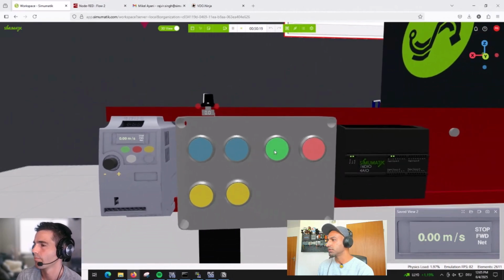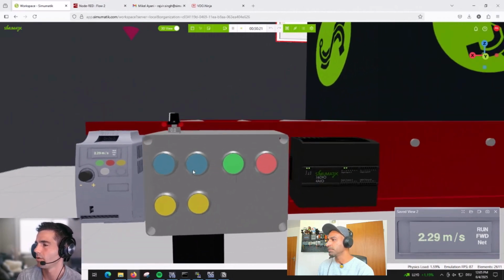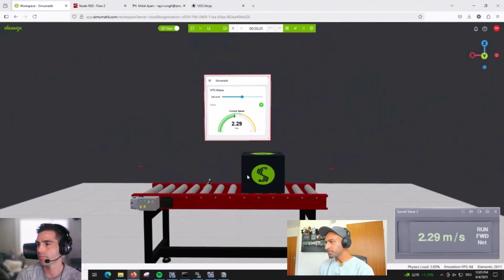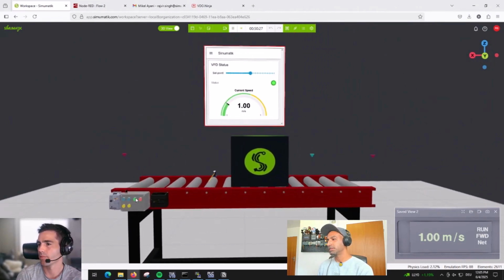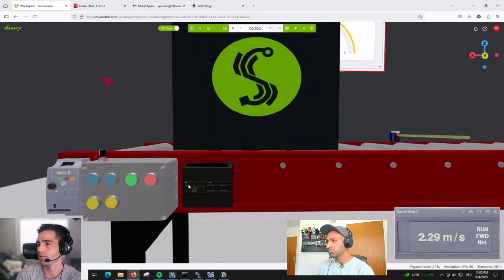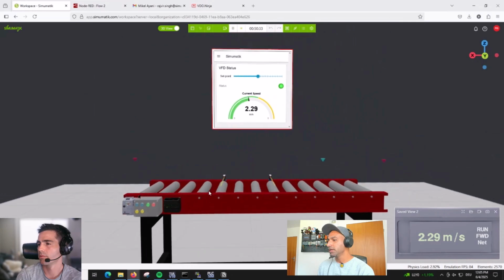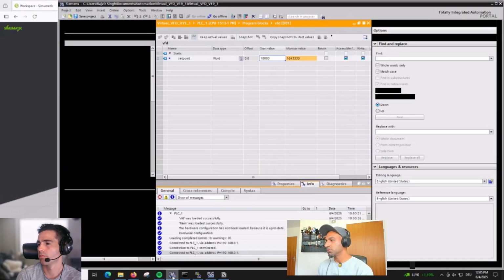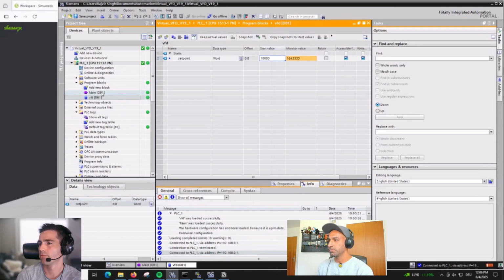So this is just simple on-off control. But the question is how the signal is moving. From these two buttons, the signal is physically going to this PLC, like a voltage, to this virtual PLC. And then this PLC is communicating to my TIA portal via S7 protocol.